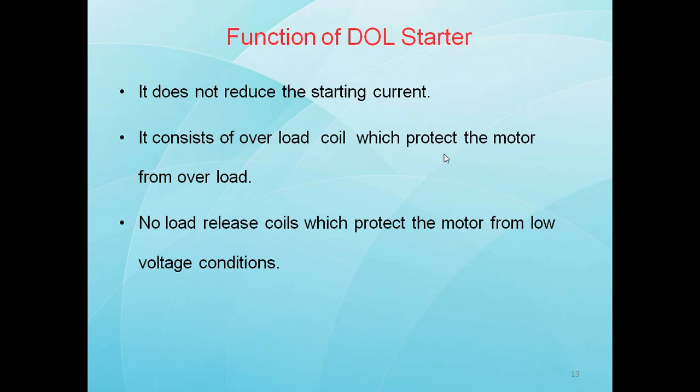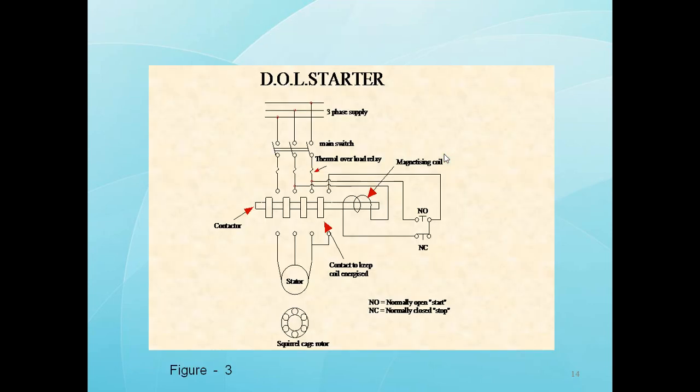Suppose low voltage comes, then the output also reduces automatically. It affects the application which is working on that motor. That's why we require the no load release coil.